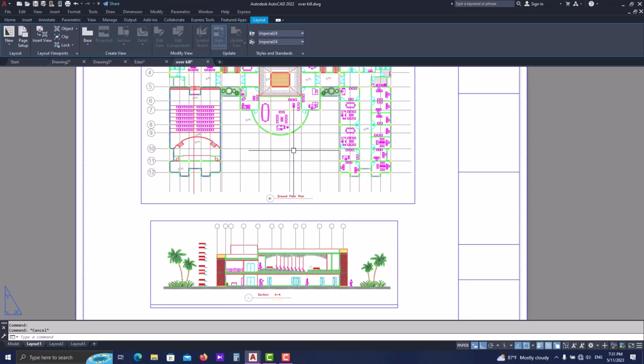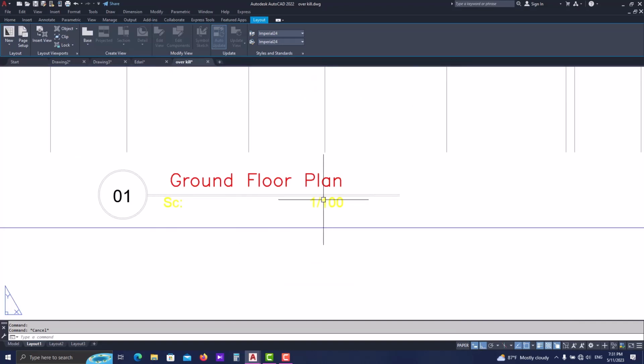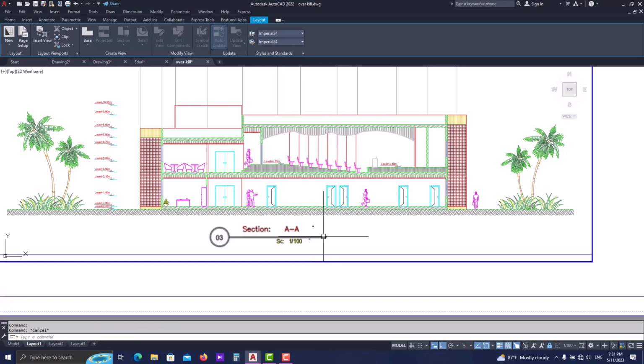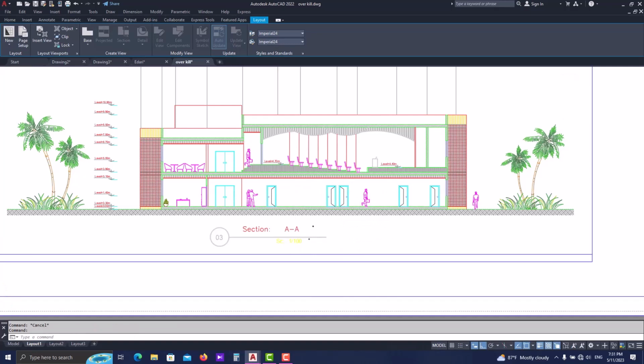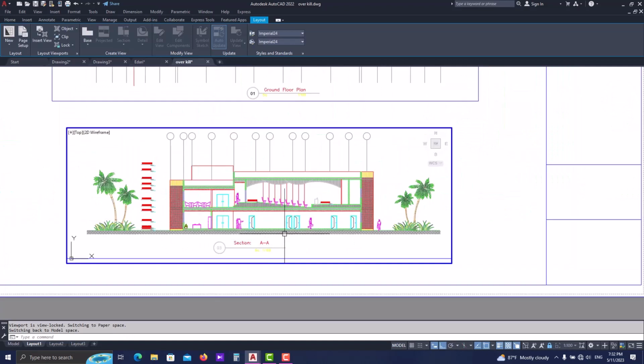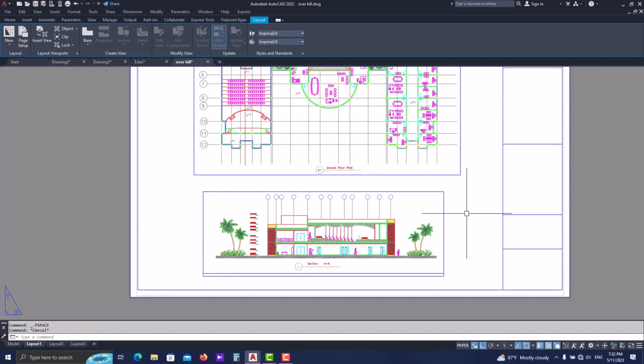And we can actually put them in different sheets and with different scales, but here we just use the same scale and the same sheet. All right, the tags here are correct, but if you wanted to change them, you can enter your viewport boundary, then do a double click on this tag. Then in the Attribute Editor window, change the scale to 1/200th, for example. Okay, Control Z. So this way you can modify your objects after you set them in your sheet.